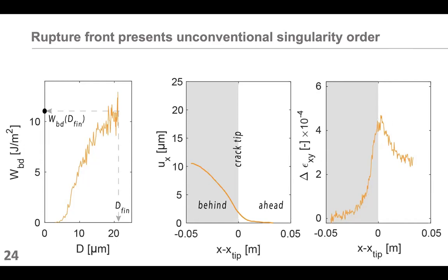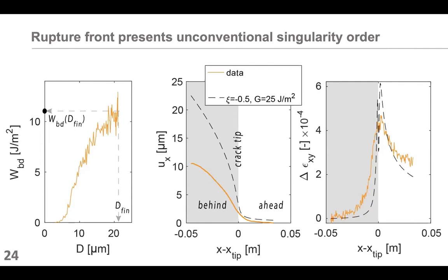So if we use the same framework that I have shown you before, that is linear elastic fracture mechanics, we can try to obtain the best fit using LEFM. And if we do that, what we saw is that it's possible to fit more or less well the strain singularity, the strain perturbation at the crack tip, but we have a strong mismatch in terms of displacement behind the crack tip.